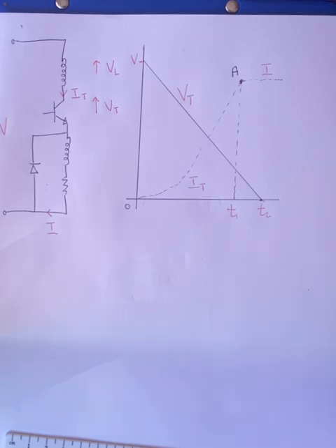Now, to keep your transients within the safe limits of a device, snubbers delay the rate of rise of either voltage or current in a device. They are fundamentally used to minimize the power dissipated during switching times by means of wave shaping. In this instance, we are going to start with what is called a turn on snubber.